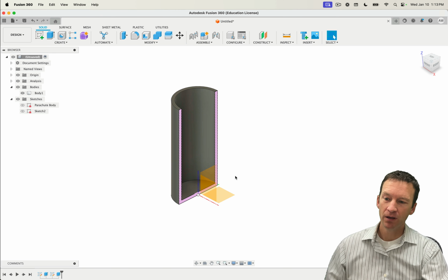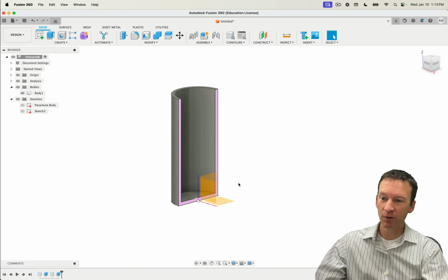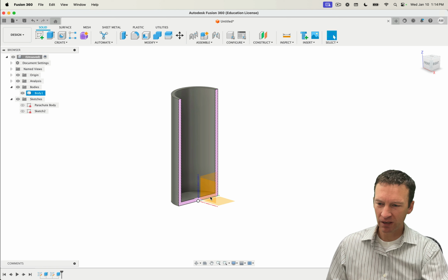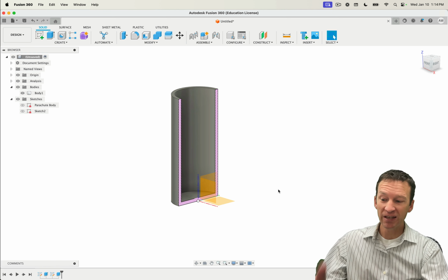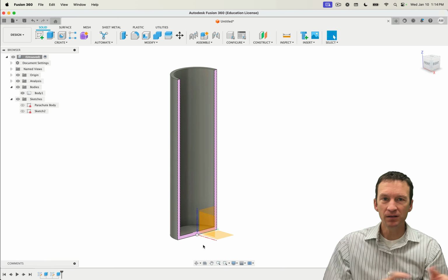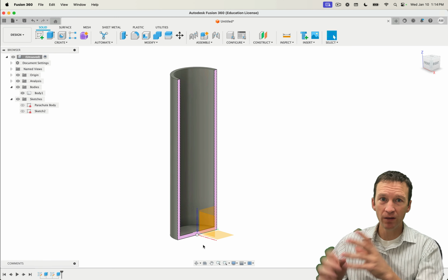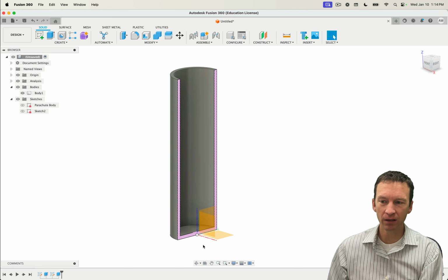See how it just went up? I called this the diameter, but this is the height. I completely messed up the name there. I was thinking we were doing the diameter here, but that's the height value, so I need to rename that parameter. Parameters can be based off of something else, which is based off of something else, and if we change one, the propagation happens and everything automatically updates.